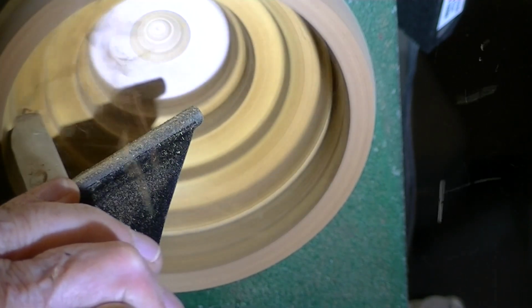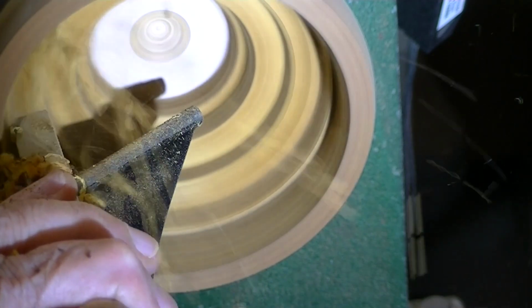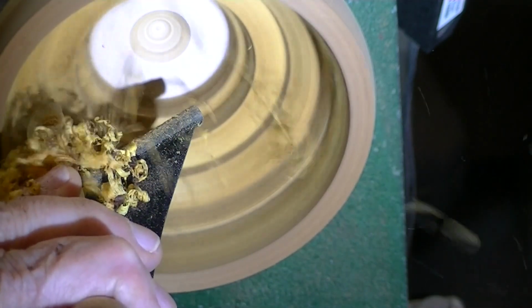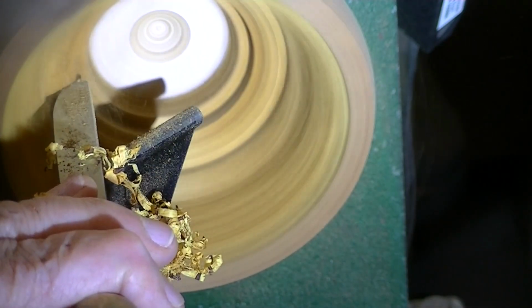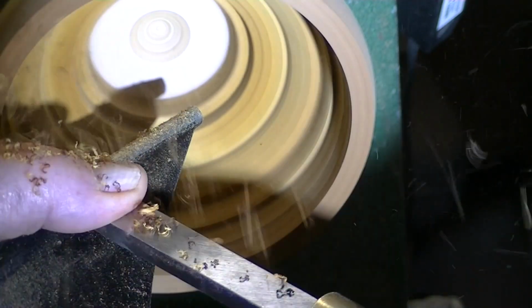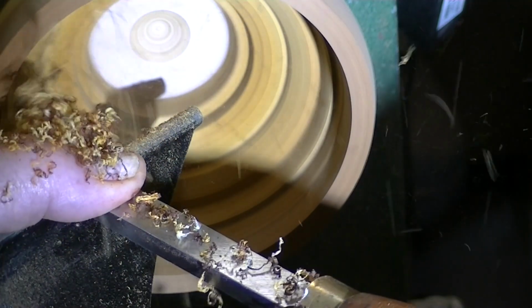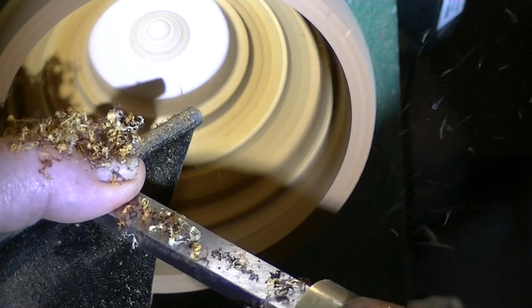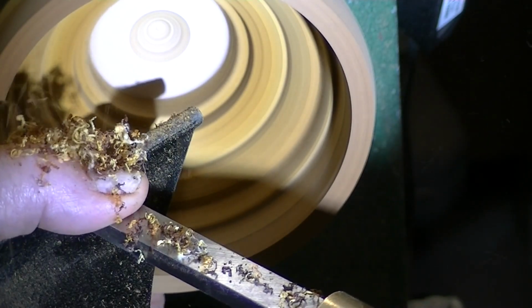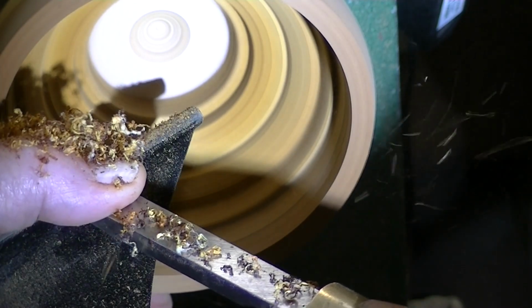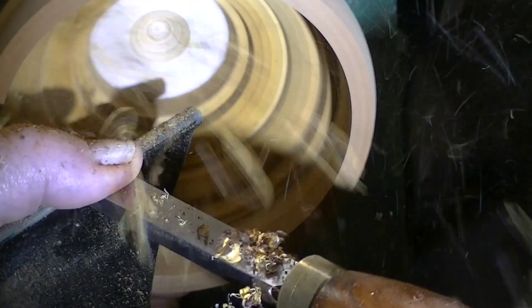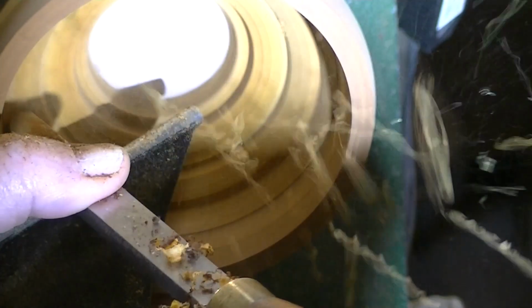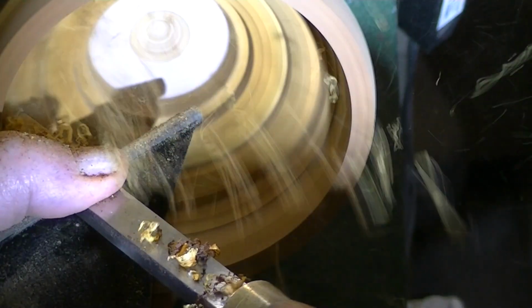And because of the way the tool rest is set, you can see that the scraper is hanging over the tool rest enough that it's causing me to not be stable in holding it. It's pulling my hand up because it's hanging over the tool rest so far. So I'll change to a little heavier tool, change my tool rest position a little bit here, and see if I can start getting cleaner cuts. My hand is resting on the outside of the vessel, my thumb on top of the scraper to help control and drive it.